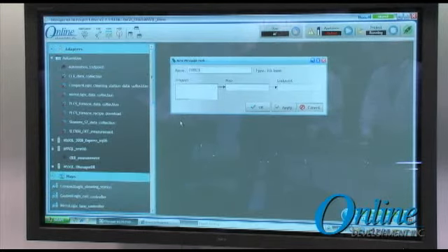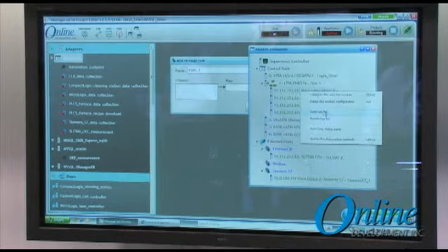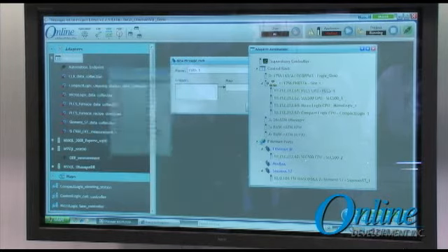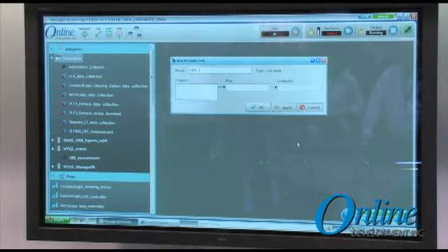But on the automation side, what I want to do first is go get information from the controller that's in our chassis. So in our chassis over here, we've got a number of PLCs, and I'm going to go get that furnace data from the PLC5 and show you that I can open the tag list and access all the memory in that controller. And we're going to use that in our transaction. And what we'll do is build a trigger associated with that PLC5. Now, that trigger could be periodic, it could be event-based, it can allow you to compare two different tag values to actually cause a trigger condition. So it's condition-based type triggering.